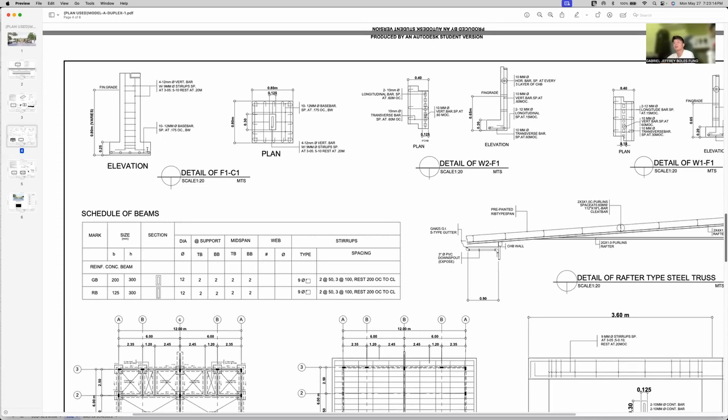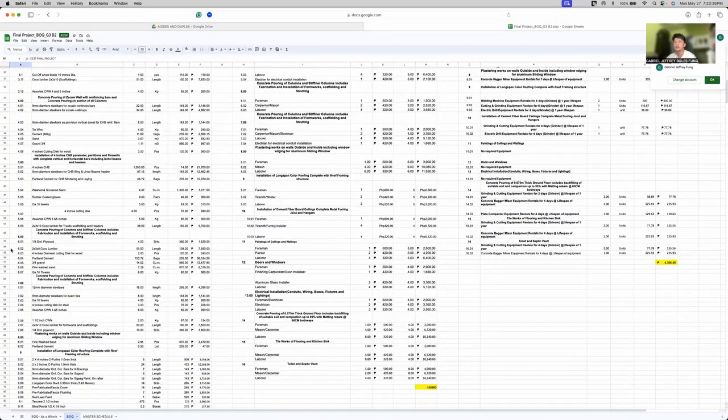By dividing that area by the effective area of the plywood, as well as some extensions to it, because we need those development lengths in order for us to nail the formworks together, we were able to estimate the number of plywood here in section 6, which is 4 sheets for the entire structure.